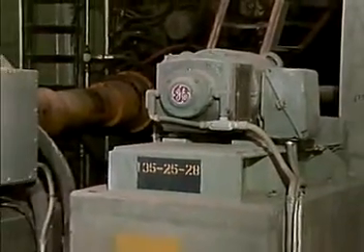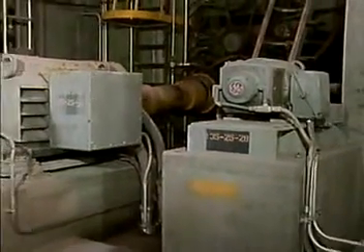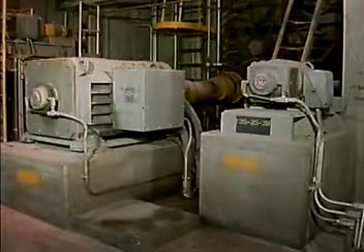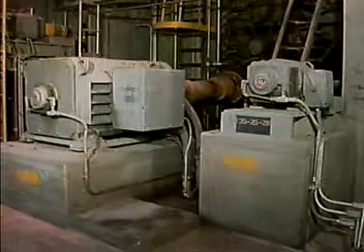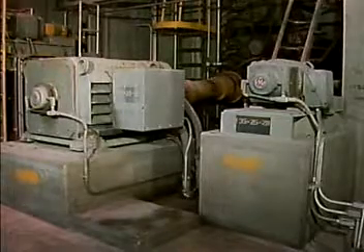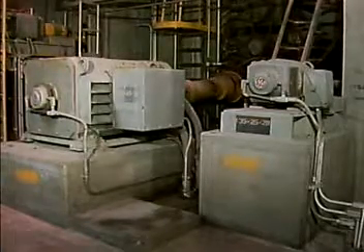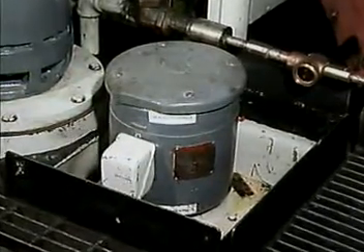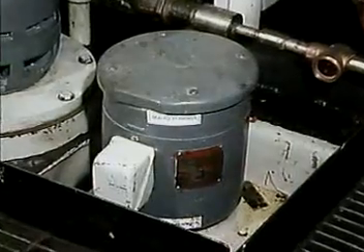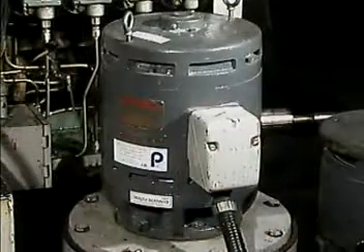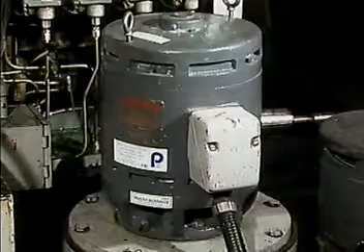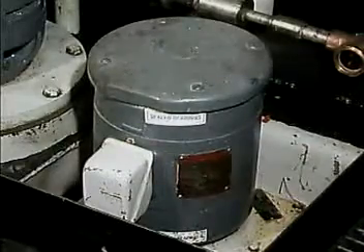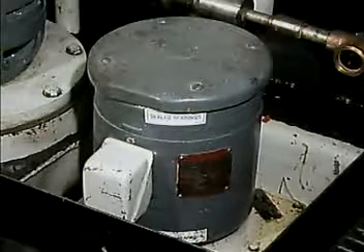Although AC motors are the most common type of motor used in industry, direct current or DC motors are also used. One common use for a DC motor is as a backup motor for a critical process. DC motors can run on the direct current supplied by a battery when there is a failure in the alternating current supplied to an AC motor. For example, this DC motor is used with a backup pump that supplies oil to the bearings in a large piece of equipment. Normally, an AC motor drives a separate pump that supplies oil to the bearings. But if that motor fails, the DC motor-driven pump can be used to provide the oil.